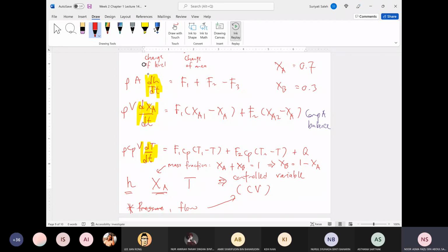Let's say in this case, you want to control SA 0.7, SB 0.6. Then we can see if we add up 0.7 and 0.6, we get 1.3, which is violating the rules. That's why process understanding is very important. We cannot simply put two controllers at once for composition. We need to check the basic rule. If we enforce it like this, then both will not achieve the desired condition.